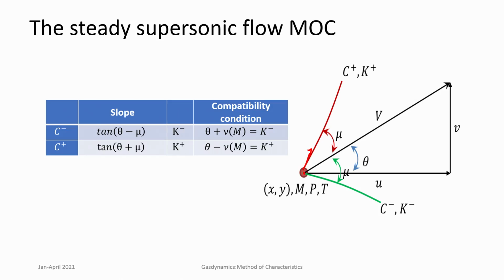But in this particular context, in the method of characteristics, you solve both the mesh as well as the flow solution, marching from an initial condition. So, forward marching from an initial condition. You solve the mesh, in this case that kind of a mesh is known as a characteristic net, as well as the flow conditions at each point.